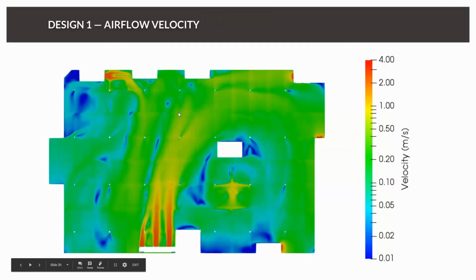Well, and now I've prepared some of the results from that simulation and created screenshots just to show you quickly which very valuable insights the simulation will provide us with. So first of all, let's take a look at the airflow pattern. Therefore, we will visualize the velocity flow field at a distance of approximately 1 meter from the ground. And here you can see how air is introduced into our garage, how it's removed at some points, and blue means a very low velocity compared to 0, and red is a high velocity of 4 meters per second.